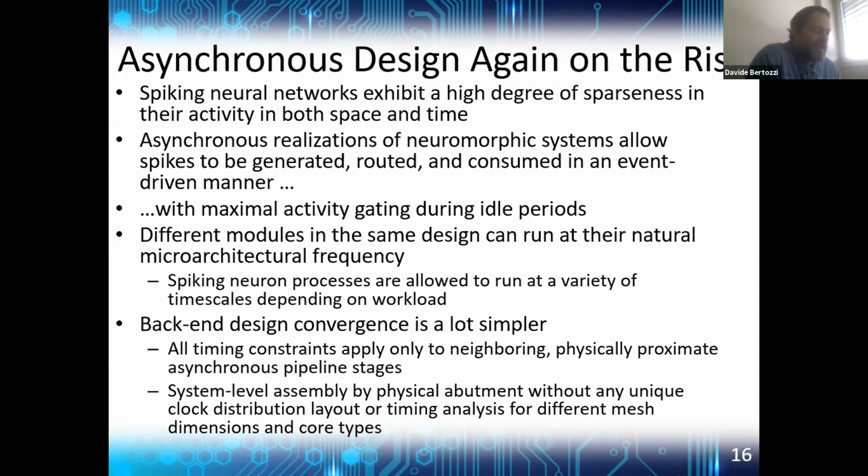Moreover, system-level design is also facilitated, since you just have to put the components together during the system-level composition phase, and these components self-regulate their interaction through a local asynchronous handshaking protocol. You have no such thing as controlling the skew and the jitter of your clock tree, which leads to power-hungry clock power instantiation.